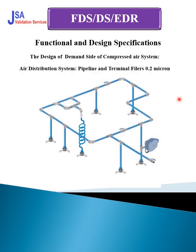Now on the demand side, there is an air distribution system and a pipeline terminal filter of 0.2 micron. That is the demand side. So your user requirement specification should mention how many points there are, which terminal filter you require, the type of machine you are going to use, and the CFM required for each machine. Then you, or the vendor, can calculate the capacity of the compressed air system.